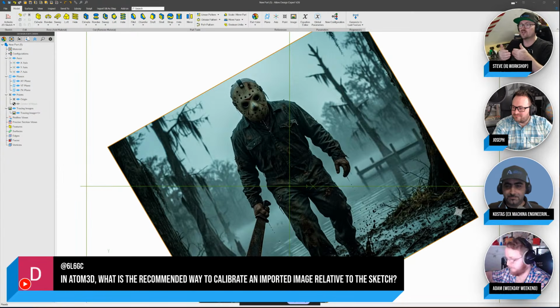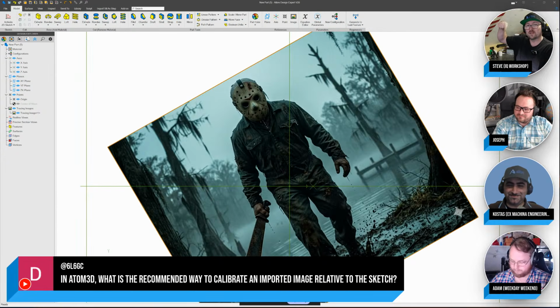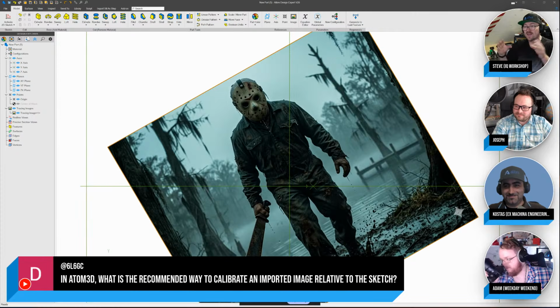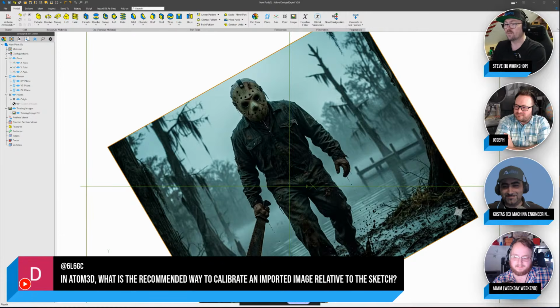What you're doing is you're compressing perspective. And that means that, again, if you're holding a 1 meter rule, you can then measure that 1 meter rule in the photograph with the minimum amount of perspective distortion. You compress that perspective. Therefore, you're going to get a more accurate image that you can come in and calibrate in Alibre and then design your part. And you're more likely to get a better fitment using those two techniques.